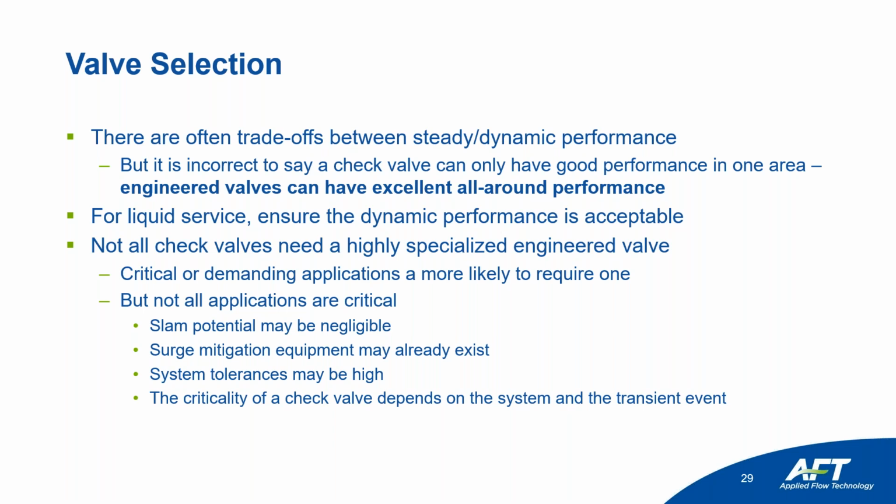But there are some situations where it's more likely that you're going to need one. So maybe certain types of surge events like pump trips with multiple parallel pumps operating, or pumping against a rising main, or just if it's a critical, sensitive application, you might want to reduce the surge, but you may not need to spend the money on that.